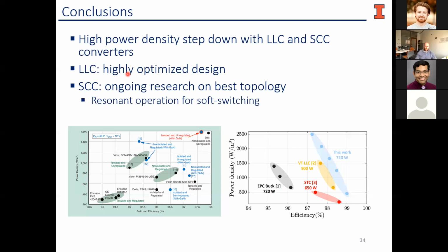At the same time, especially if we look at, say, the EPC Buck here, this has 5 interleaved stages. If one of those goes down and at least doesn't fail as a short, you could take one of that out and the rest of the converter will still operate. If you look at most of these other converters, if one switch goes down, the rest of the thing goes down. So these designs definitely are not a modular design, although obviously they could be at a certain point. The EPC design here, for example, does have a little bit of modular capabilities.